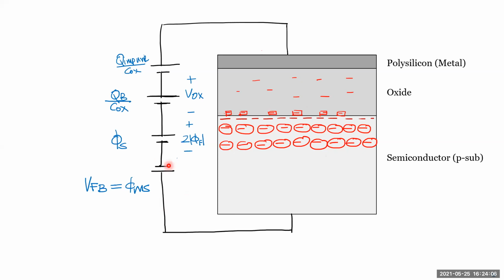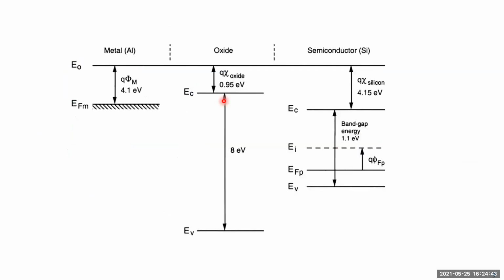So you first come over the flat band voltage, not first, but in series basically, and then you give the voltage to come over this impurity charge. For example, if this was positive charge, then this would be reverse. Then the voltage required to bring this potential to 2φf, plus the voltage required to create an electric field such that you create a depletion region here. So it's convoluted, and that's your VT. That's your expression for the threshold voltage.